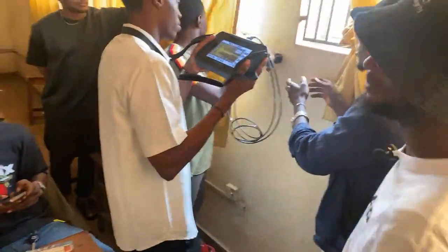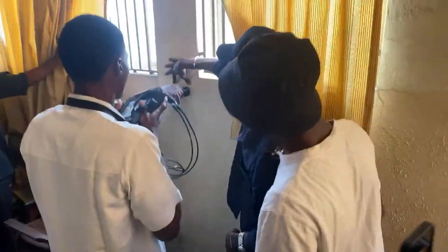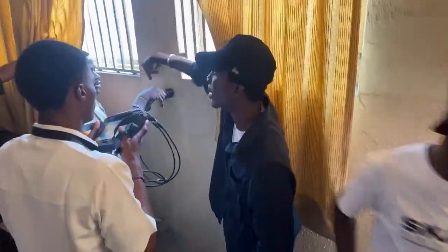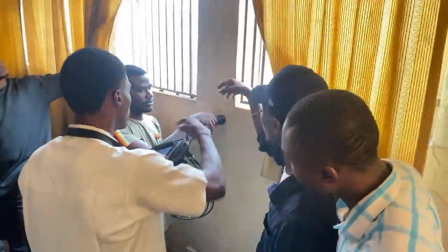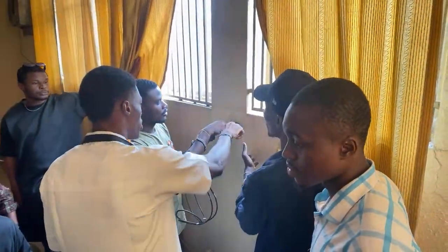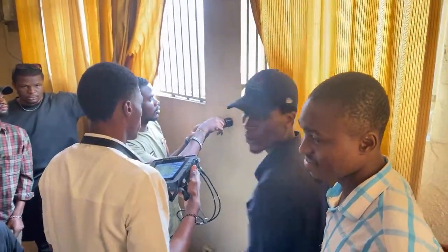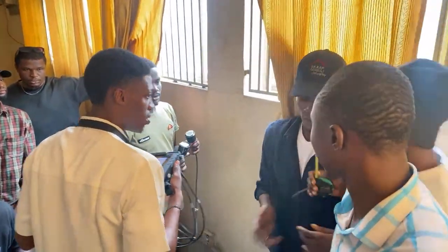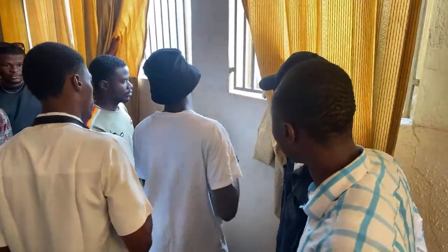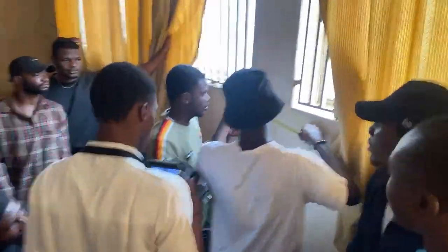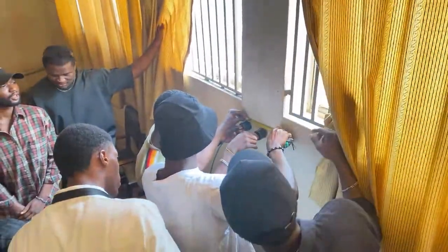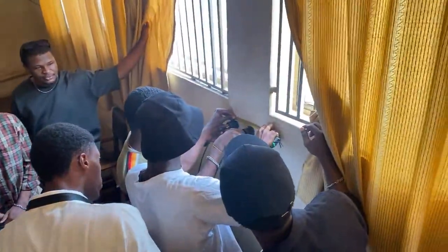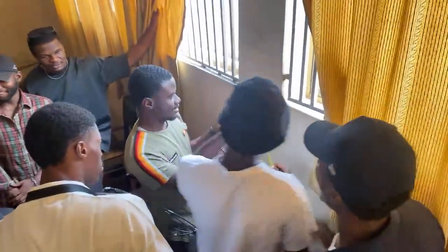Now you don't need to press it, just hold on. Now, is this up to 120? The path length between this transducer, from center to center, should be 120 mm. If you want to get it, I don't believe it's up to 120. So you can just use a tip. Center to center. Can you see this first center? Yeah, this is 120 here. That's 120. All right, so this is 120 mm.